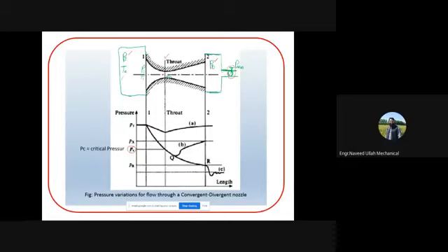And in the same way, if you want to know about the under and over expansion case, this is based on this back pressure. So having this valve, you can decrease this back pressure. Let's say for example, if your P1 is equal to PB, there will be no flow through the nozzle. But if you decrease this PB, there is a pressure difference, and the flow will start.